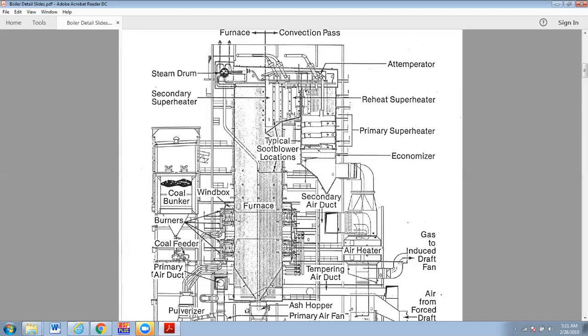We're coming on across, and we come down. We've talked about the temperatures along the way, but of course that's on the steam side. So this flue gas is just passing across these various tubes, and the enclosure is lined with tubes as well. Then we come down across additional surfaces. We've got the primary superheater, and then we come down across the economizer. So again, we're sucking heat out of these gases, trying to be as efficient as possible.